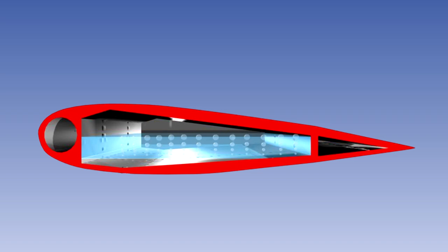The temperature at which a liquid boils will reduce as the pressure on its surface reduces. As an aircraft climbs, the pressure on the surface of the fuel reduces, and with that reduction comes an increased likelihood that the fuel will boil and form vapor in the pipelines.